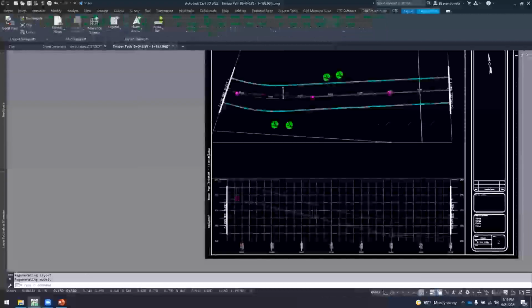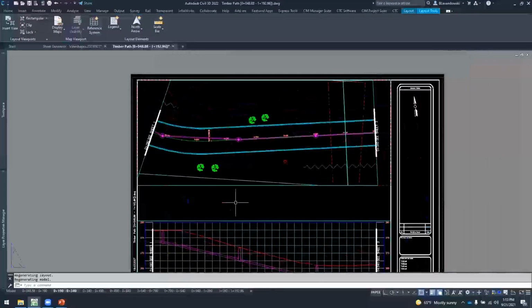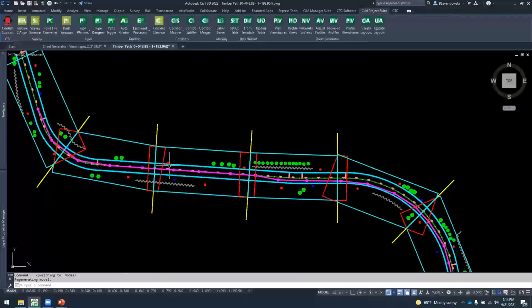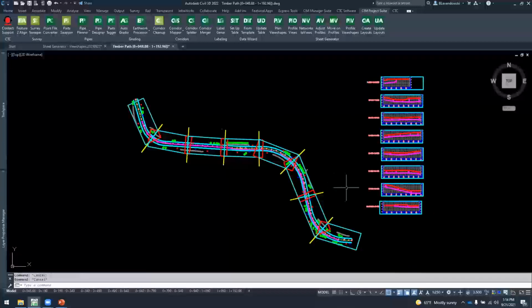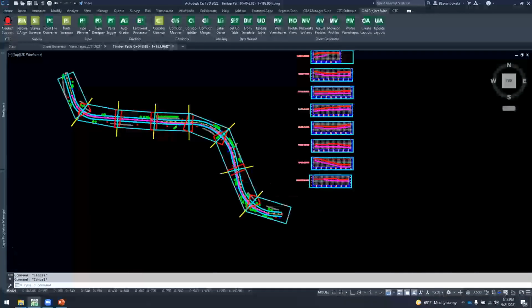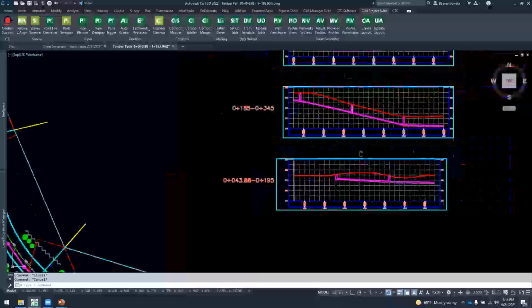And if we look at our plan views now, we know everything is screwed up, right? This line here is what my new viewport position and rotation should be. And here is what it is currently. So we're kind of wreaking havoc on everything. I shifted everything 20 meters in plan view. I've got to do the same in profile view.